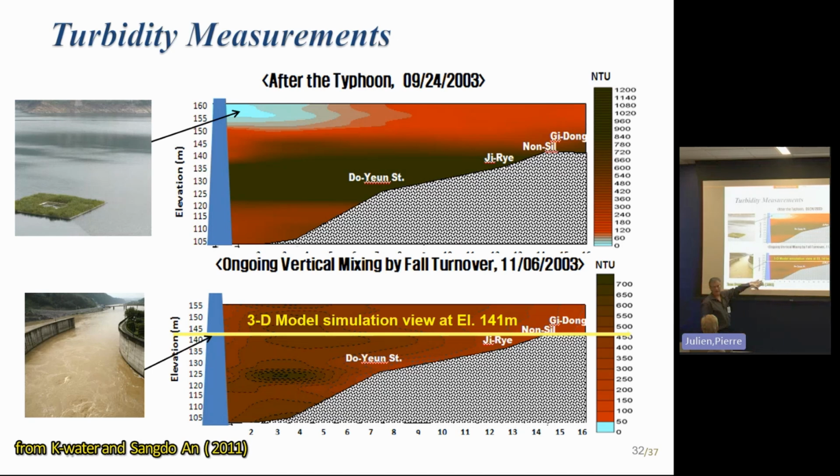So if you have a reservoir that's from 150 to 110, let's say 40 meters, you're looking at a month for the sediment to settle out. So it means that if you have a density current like this with very fine particles like clay, then you're going to get that problem for a very long period of time. And you try to solve this thing, right? So the question: do you have silts or do you have clays?